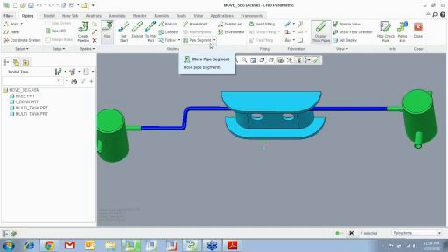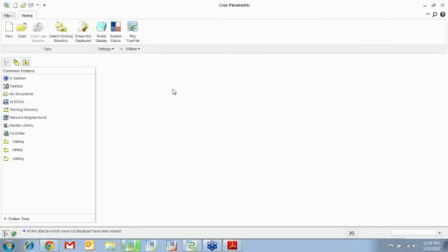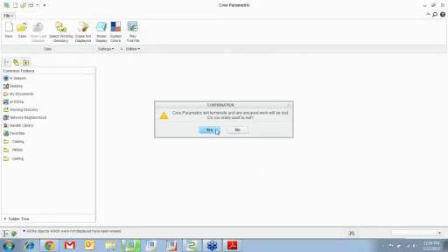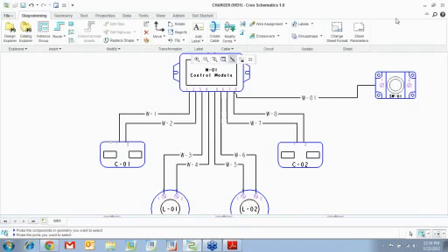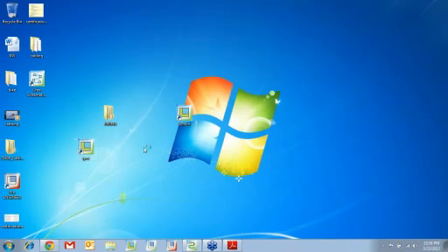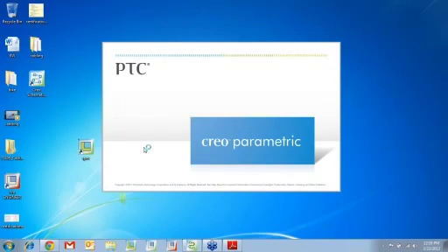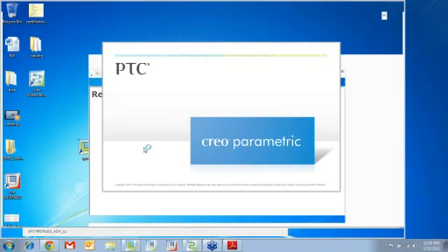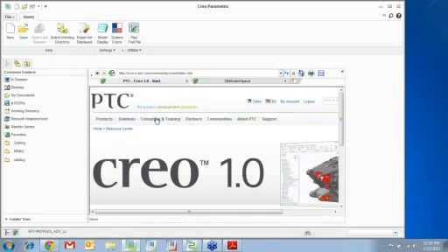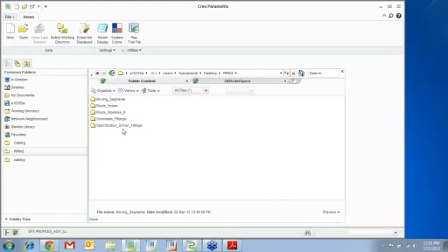So the next thing that we have after we do this is to do a spec driven piping. Let's do spec driven first, and then we'll do a schematic driven. In a spec driven piping, what I do is I basically go ahead and set up the specs for a certain pipeline. Say what type of fitting to use, what sizes I should use. So once I set up these things, my usability, ease of use is very high.